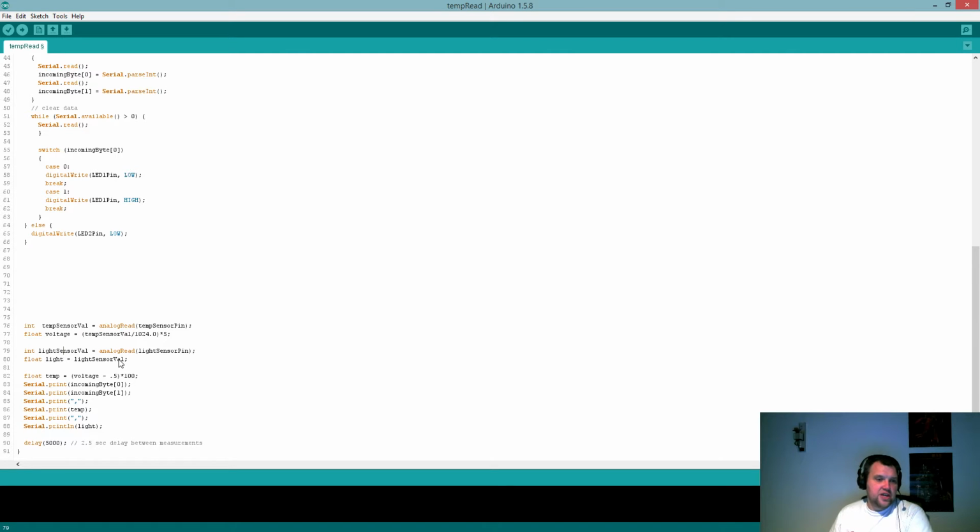We just turn the light read into a float, and that's why we get this nice number. Otherwise, you would get something like a number between 0 and 1023. So yeah, what's that? It's easier to say, well, if we turn it into a float, we can say it's 100% or 0%. And what we saw was kind of 83% resistance. That's easier to understand.